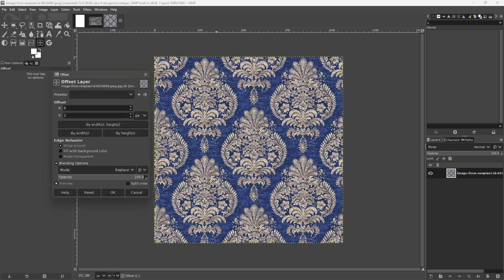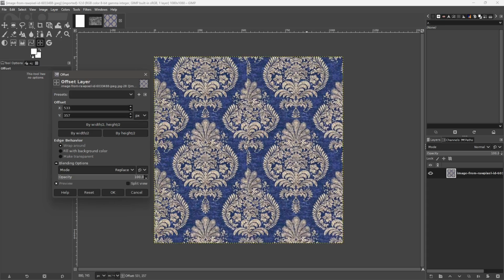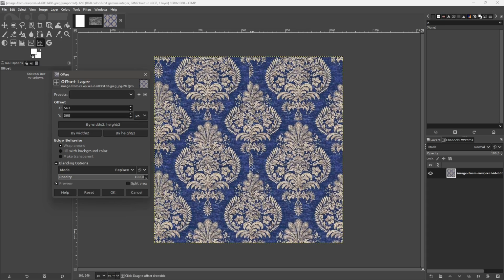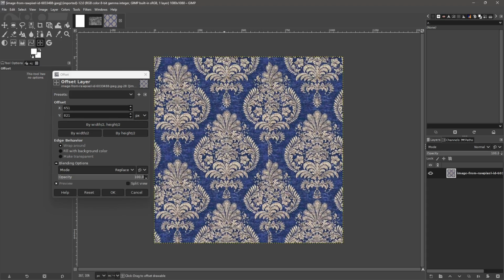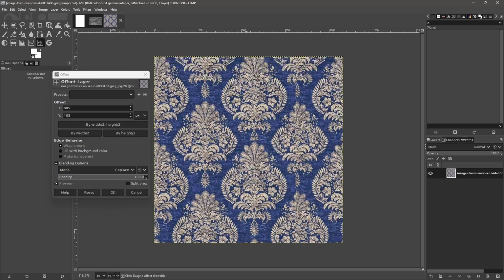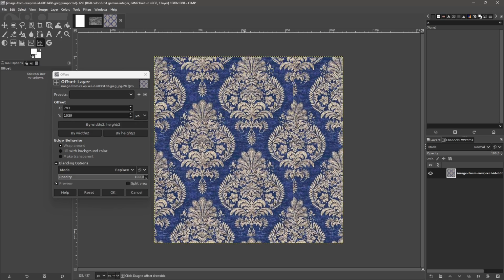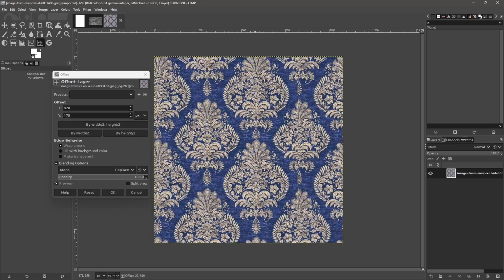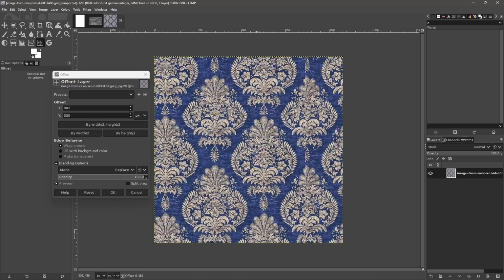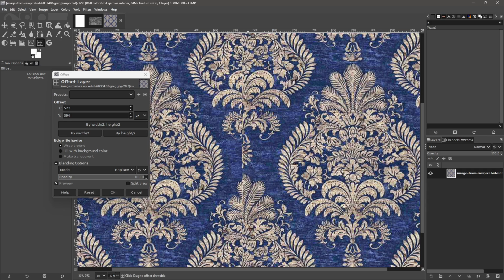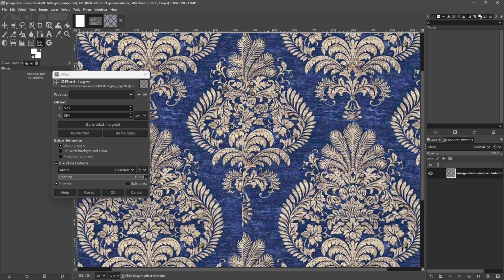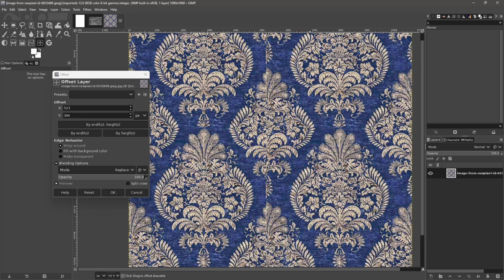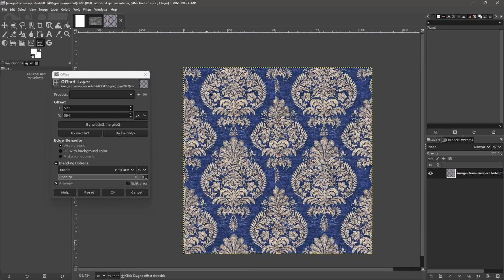So if I click and drag, you can see that there is actually a cut right here. We don't have any horizontal cut. So the tile is gonna work good in vertical, but you see this is not good. So this is not a good texture. And also here I can see now the horizontal cut. So this is not correctly repeated. So you need to make sure that your textures are seamless if you want to repeat them in a correct fashion. Otherwise, you need to fix this.